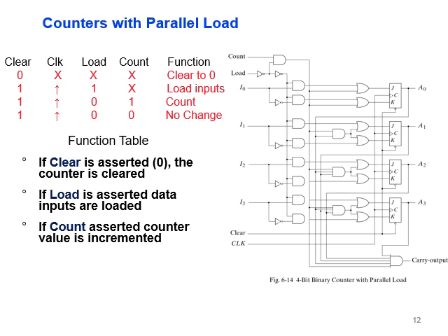And this can be discussed through this summary truth table, or let me say state table. When clear is 0, all values will be 0, regardless of the clock; the load and the count are don't care. And if clear is 1, see the 3 cases, look at the clock. If it is positive or rising, then we have these cases. When load is 1, input the load and don't care about the count. When load is 0 and count is 1, then do counting. When both of them are 0, don't change the state. Keep it as it is.